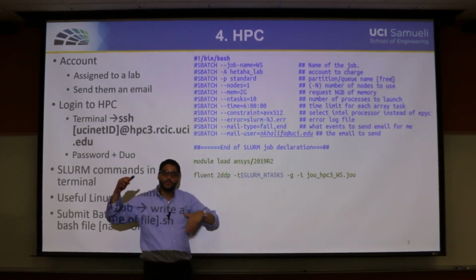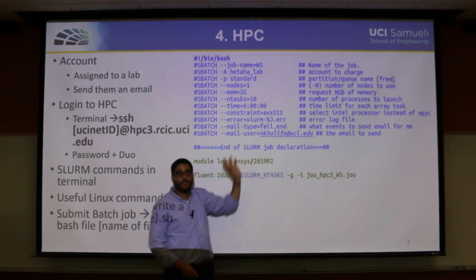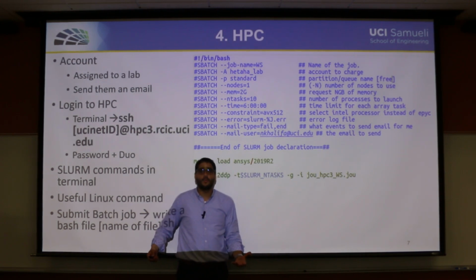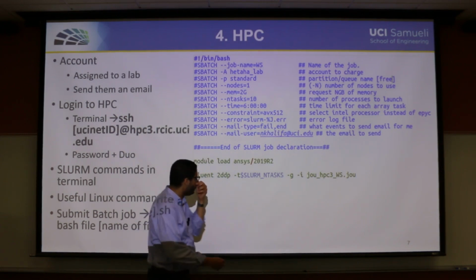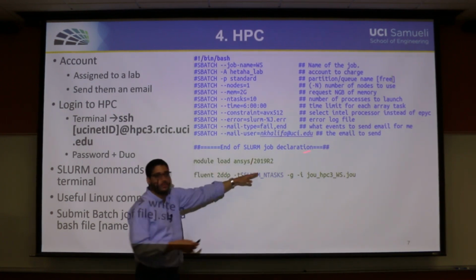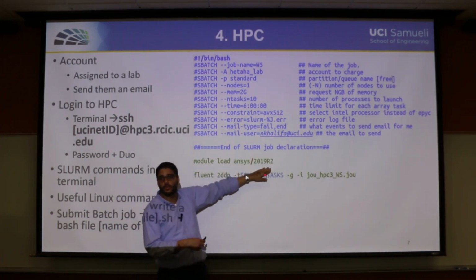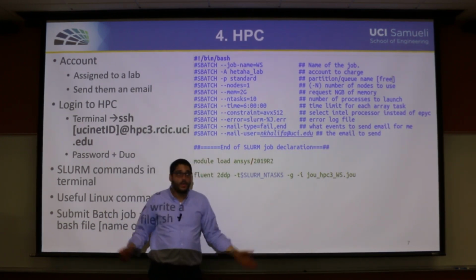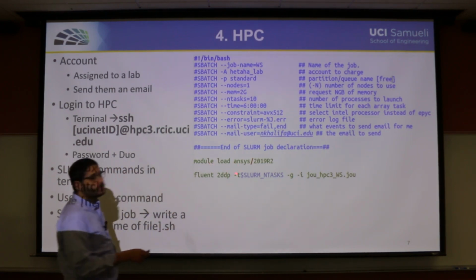Okay, because in a lot of cases you could get confused, and for example you might ask for 5 cores, but you have here 10 cores and Fluent will not open, because the environment that the scheduler prepared for you is as if you are running Fluent only on a computer with 5 cores. Okay, and without the graphical user interface, this is the input file and we are done. And module load, please load the ANSYS module, open ANSYS, this is the already pre-set up or pre-installed software on the HPC, and just that line that we used to do. However, the experience or the knowledge comes in here. Okay, you need to declare most of this stuff, if not all.